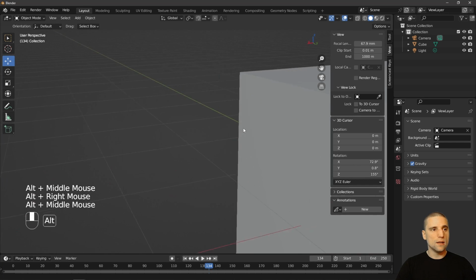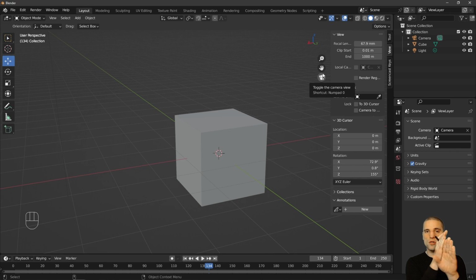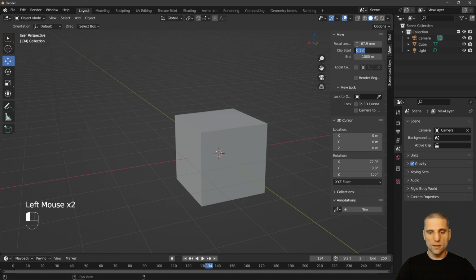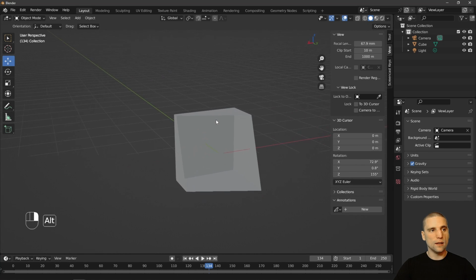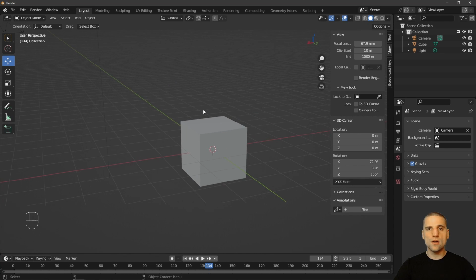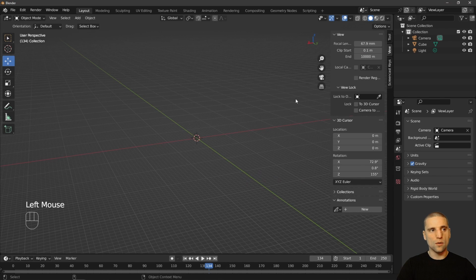Clipping plane is useful if there are objects or geometry right on top of each other and the images are flickering. All you have to do is bump that up to 0.1 and it stops it. If I go to 10, you can see that as I get closer, it clips into the object. So that clipping plane is useful as well when you're rendering things out. If it's a big scene and I have to zoom out but still need to see more, I'll just add one more zero or two more zeros. So that's the clipping plane. It's just what your camera can see at certain ends of its field of view.